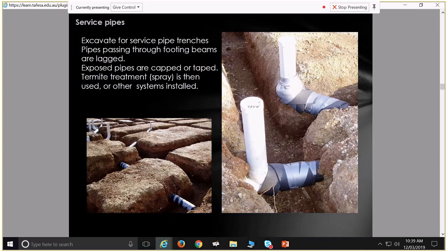And also, I've seen some shockers on sites, people putting in the steelwork for your slabs. They work fast, they work hard, they'll move several ton worth of steel and install it in about 4 or 5 hours. They're going flat out, and to be cost competitive, they do that. But in that process, they're walking over all of this stuff as well. You see pipes bending like this, and you think, do we have any cracks opening up in these pipes at that stage? Because it is incredibly important to protect your pipes